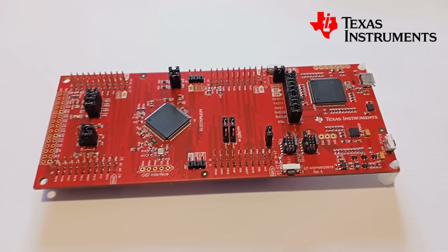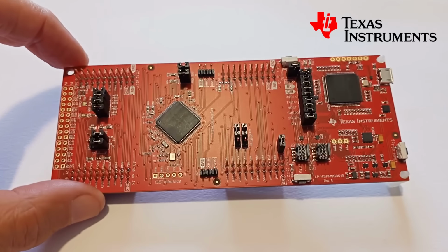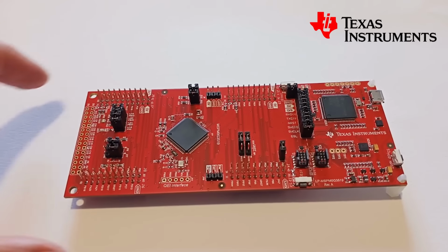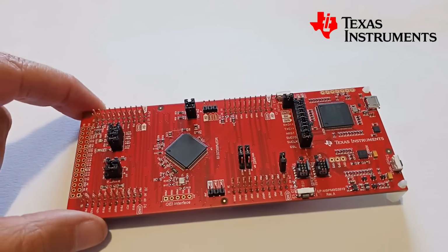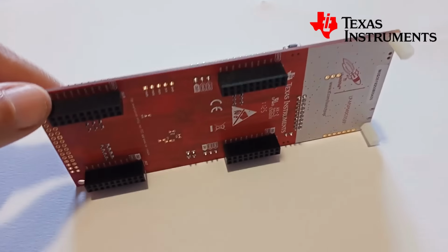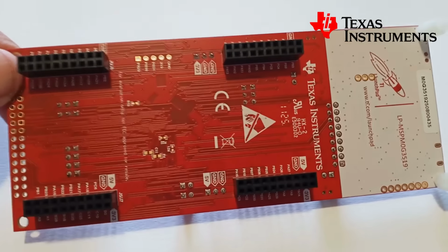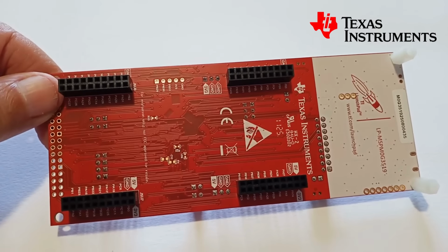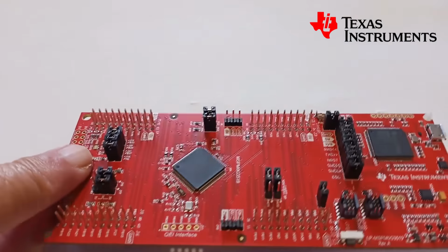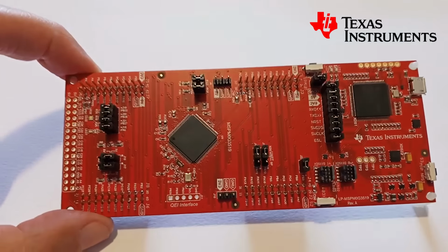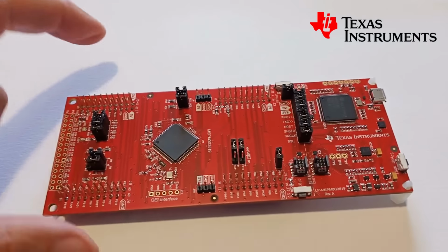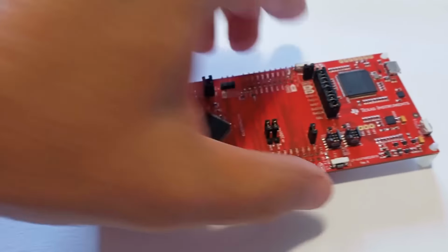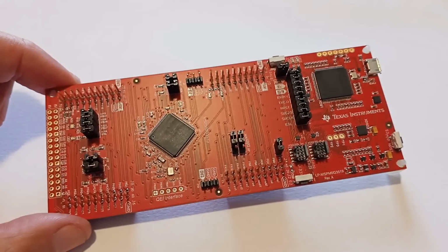The LaunchPad LP-MSPM0G3519 development kit is an easy-to-use evaluation module based on the MSPM0G3519. It contains everything needed to start developing on the MSPM0G3519 M0 plus MCU. The board includes 3 buttons, 2 LEDs, one of which is an RGB LED, and over 80 pins. Analog measurements are enhanced thanks to optimally placed ADC and DAC low-pass filters.